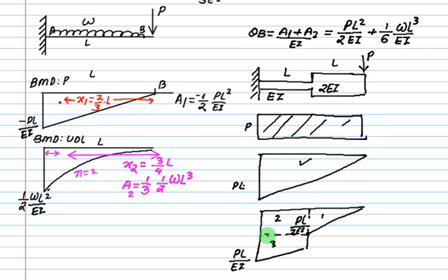Is the concept of EI clear? You have to construct one more figure. But when EI is uniform, you can use the BMD itself as the curvature diagram. But suppose in the problem EI is different, then construct the SFD, then the BMD, and then the curvature diagram when EI is not uniform. Okay? Then your answer is correct. Otherwise you may be wrong.